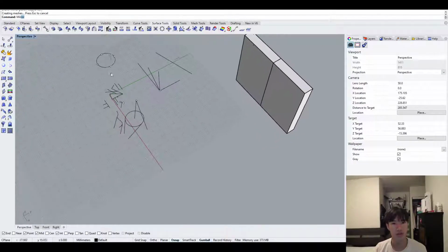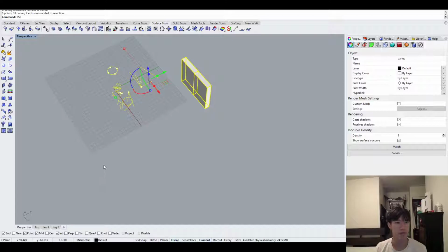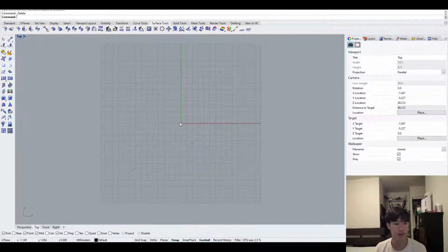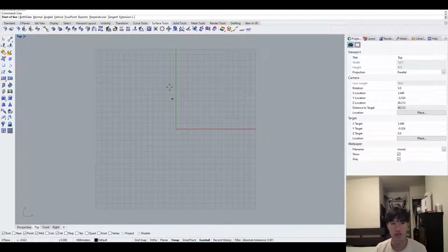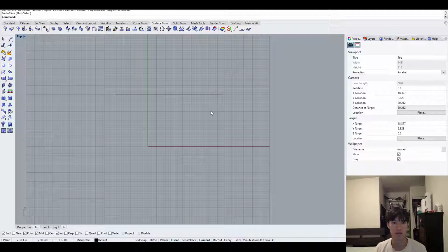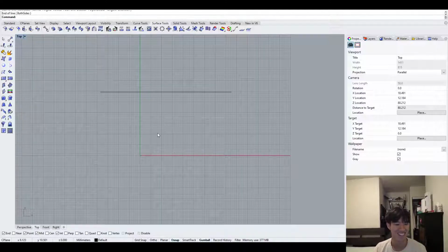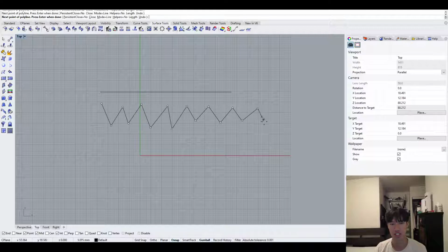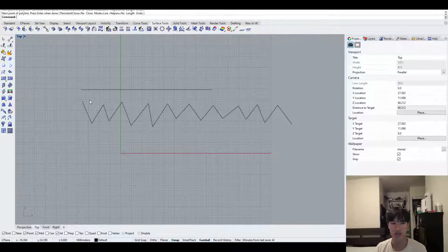Yeah, let's go through a couple of the basic ones for 2D drawing. Right, so the one we'll be using this whole time is line. There's also polyline, which allows you to draw collections of lines, as long as you keep clicking and then you press space or enter to end your drawing of your polyline.